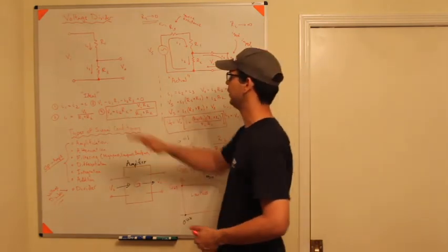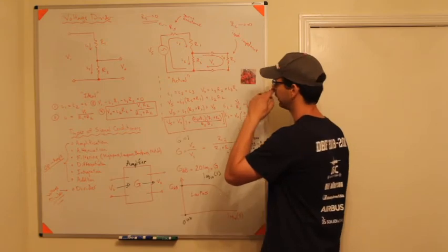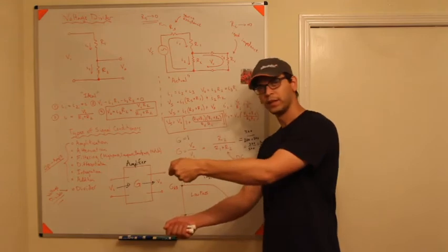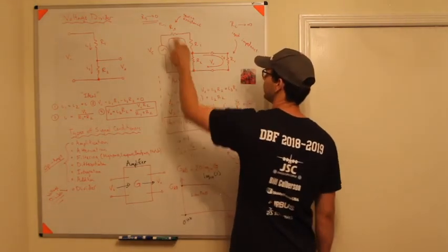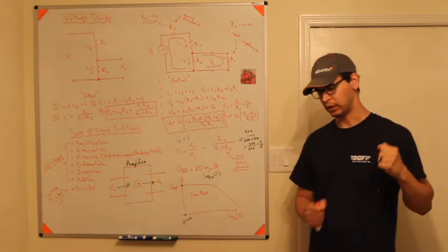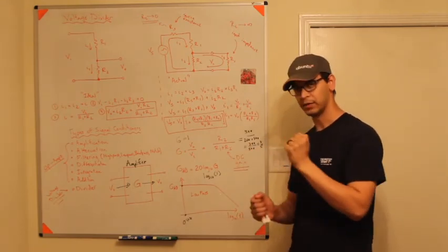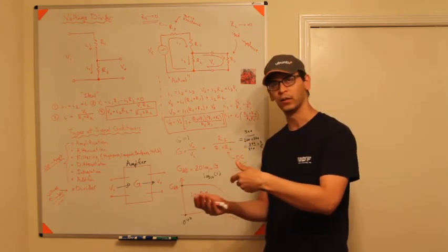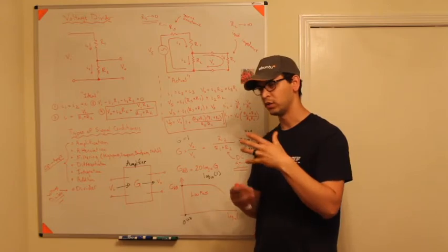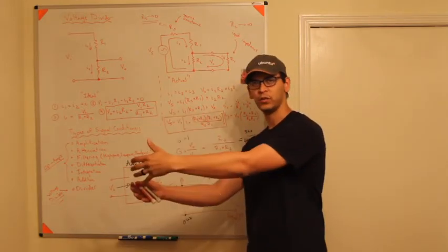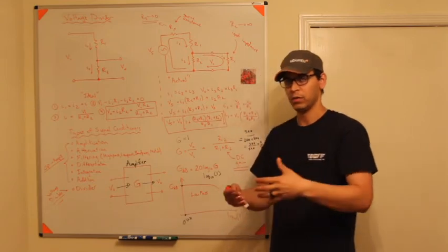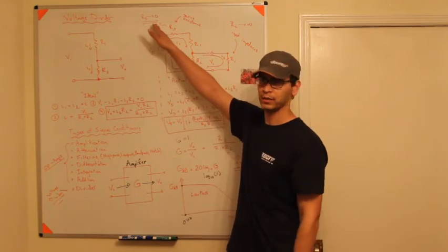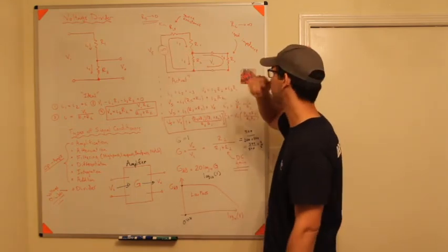Now this is the ideal scenario. Let's look at the actual signal for a second here. Whatever you hook this up to, any voltage source is going to have source resistance. That means that if you deliver power to something because you're trying to turn it on, there's going to be some source resistance, the wiring or whatever, so you're going to lose energy as it transfers to your system. In this case, resistance is bad, you would like this resistance to go to 0. You'll see in these equations later how that all works out.